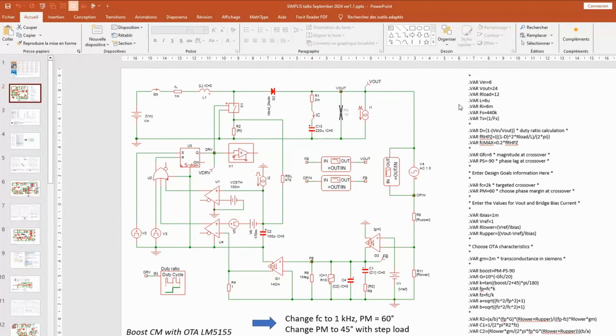And you have to make sure that stability is always correct in terms of phase margin, gain margin, and crossover frequency while these elements are moving. So the goal of the compensation strategy is to neutralize these stray elements. And I do that here by automating, as you can see on the right side, using a control block and not the F12 window, because I like to see things on the schematic.